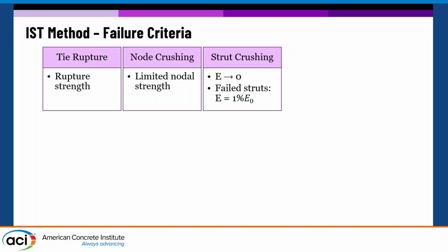So then I have to go back a little bit to your formula there, because you're assuming that the section is already cracked. Cracked, not crushed. Yeah. You don't have any assumption for when it is not yet cracked? No, all the equations become more complicated. We try to make it simple, so we assume it's fully cracked. Also, fully cracked would be an extreme case, and it's a lower bound solution.